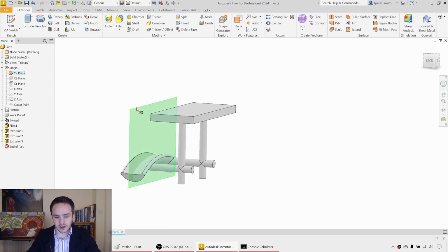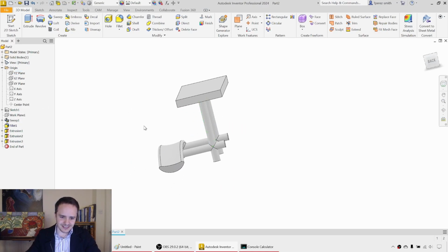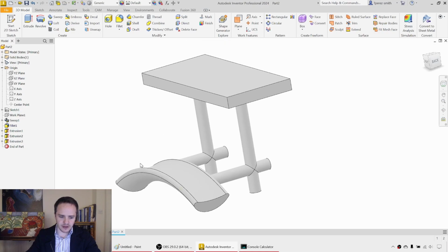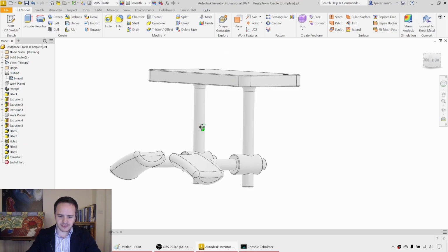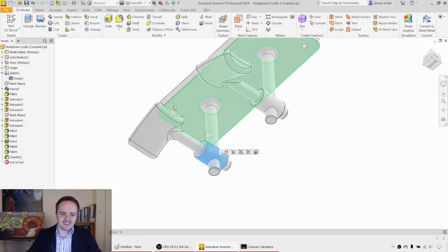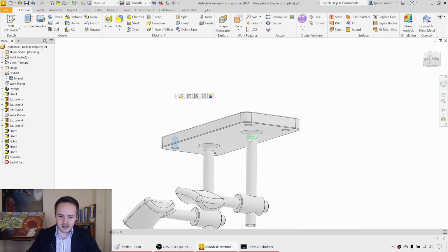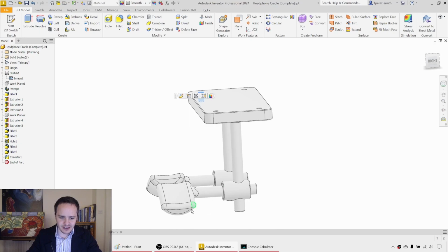Okay, and we're going to hide that origin plane by selecting it either in the graphical window or in the list. Right-click it and untick visibility. Good. Okay. Let's have a look at some of the other features that we've got on our completed model. So as we can see, we've got a cool barrel here that provides some structural reinforcement. We've got some fastener holes at the top plate, and we've got fillets and chamfers all around. Let's go ahead and detail those things.